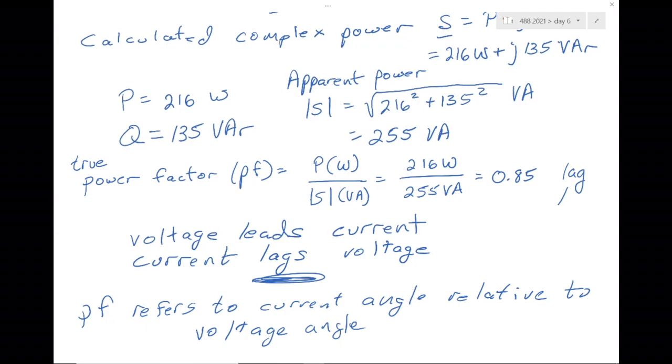it's lagging. There was once when I was in an industrial facility, and I was there because they were confused about their power factor. And they thought they had a 0.9 power factor. And they thought it was 0.9 lagging, which was a reasonable thing to think because they had lots of induction motors. It turned out it was 0.9 leading, and when they tried to correct the power factor, it reduced it because it reduced it leading. I'll give you a demonstration of this.